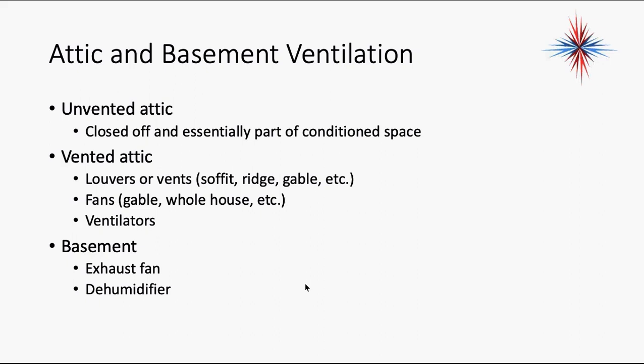Basements, if they are vented continuously, they are not part of the conditioned space. Now, that brings some additional problems in as well. But if they're not vented, they are considered part of the conditioned space. We use exhaust fans, we use dehumidifiers for basement ventilation. But if they are not vented, they are part of your conditioned space. Conditioned space means areas we have to worry about when we're sizing our equipment.